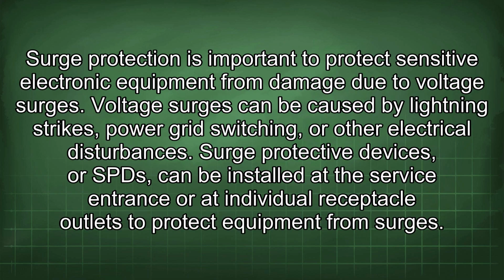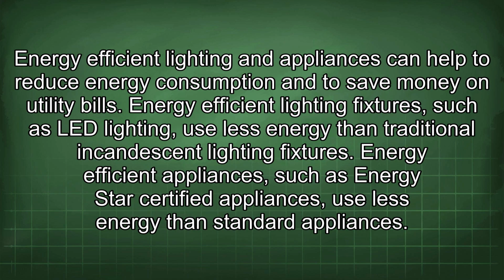Surge protection is important to protect sensitive electronic equipment from damage due to voltage surges. Voltage surges can be caused by lightning strikes, power grid switching, or other electrical disturbances. Surge protective devices, or SPDs, can be installed at the service entrance or at individual receptacle outlets to protect equipment from surges.